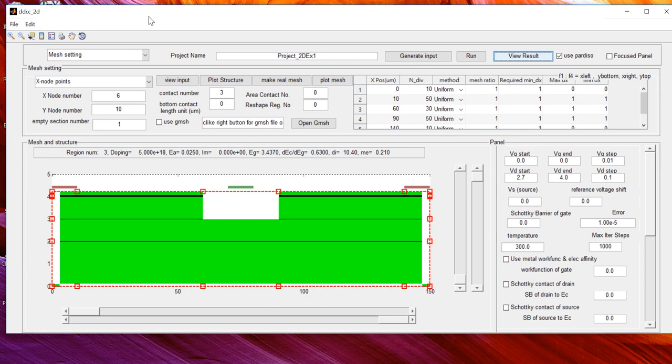But tunneling junction is usually not supported well by most solvers, because you need to tune the band-to-band tunneling parameters. If you remember, yesterday I told you there are band-to-band tunneling parameters, and you need to tune the factor. So here we assume ITO to be an equivalent P-GaN layer, but with ITO's conductivity.